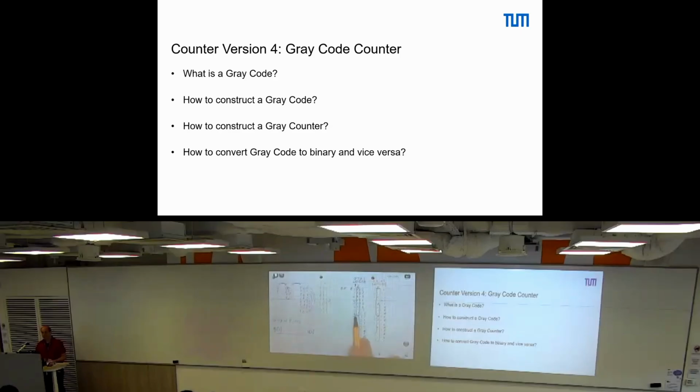The first bit actually tells us in which part we are. So we can go from here to that just by an XOR. We take G3 and another input G2, XOR them together, and the output is B2.